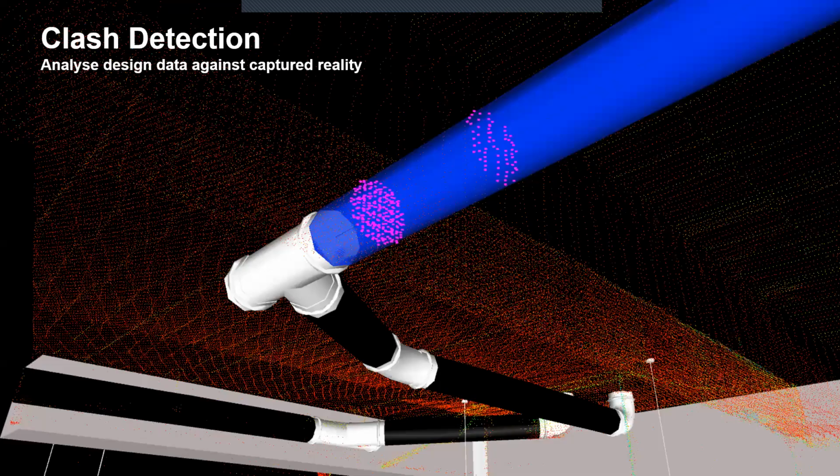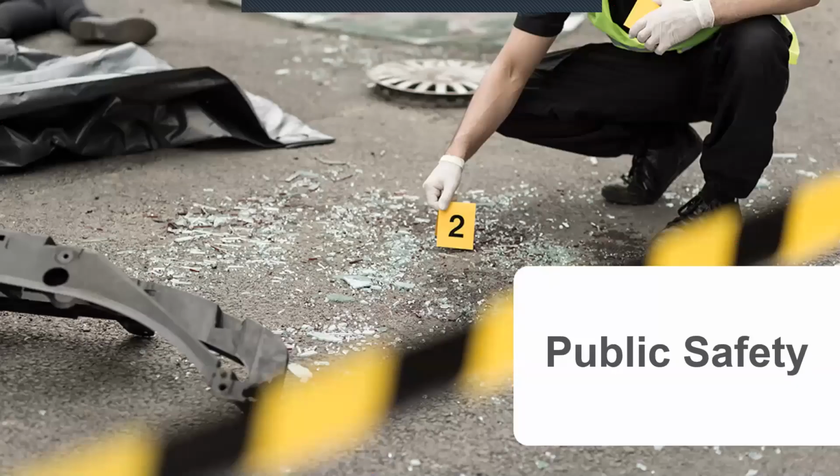And when we put all those things together, we actually get data where we can see where things are wrong and where things are right, whether there are components that are missing or components that will be clashing. In this design, the piping design says the pipe has to come like this, but in the real data the beam is constructed here, and because of this pillar over here, a slab is touching this pipe. So this is an area where the clash will be. So it gives you an early warning for clash detection so that you can have a workaround.